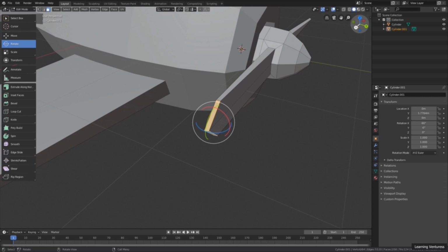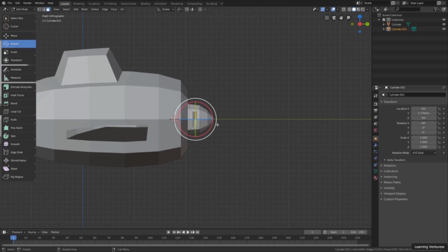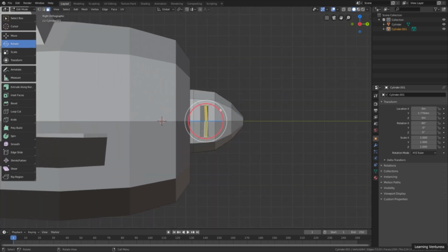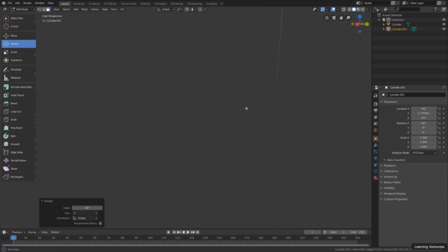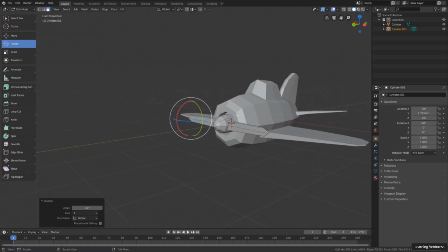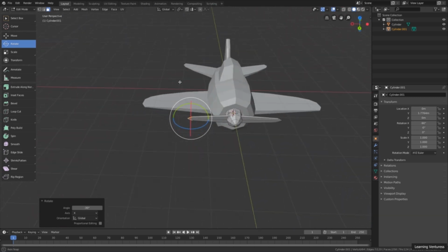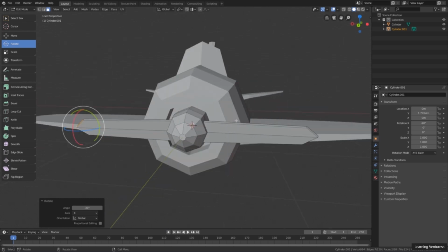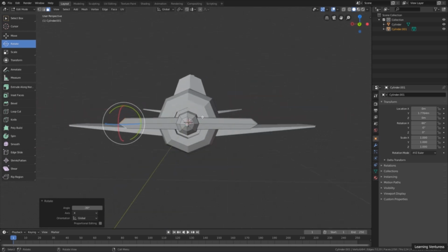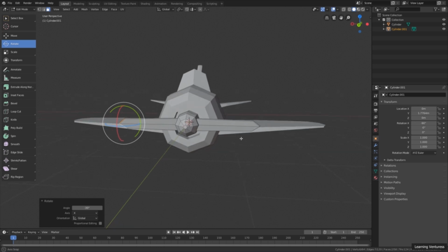Now I can position the 3D view on this side by clicking on this red circle with the X. And now I'm going to click and drag the X-axis again with the Ctrl key pressed, and I'm also going to pay attention to use 30 degrees, okay? So now we have the points of the helix twisted, and now it has the shape of a real helix, okay? And now we can start to create that drop shape that we have in the helices that grows a bit and then shrinks on the two sides.